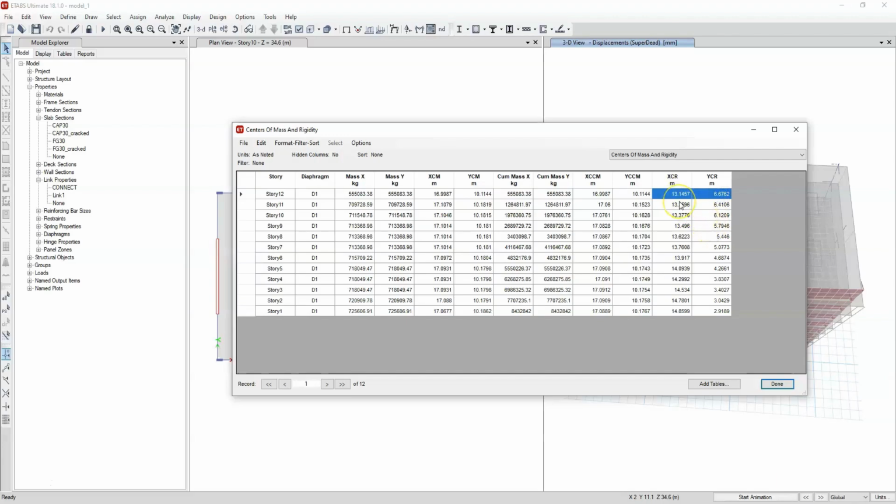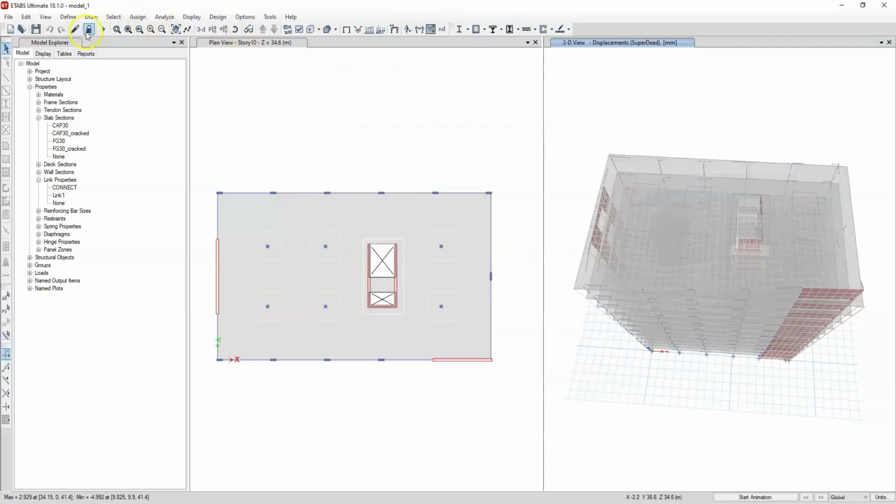And why are we going to use this? The strategy is to export these tables, and, on the one hand, we will have the centers of rigidity properly calculated along with the displacements in each story, which later allows us to calculate the translational stiffnesses of each story. But also, while doing the calculations, we are going to apply our initial loads at the top of the roof, applying the forces at the center of rigidity. And we are going to memorize the coordinates of the top story of the roof, so that it is possible to apply the loads on the top story to serve as a force reference, so we can later have a force-displacement relationship to obtain the stiffnesses.